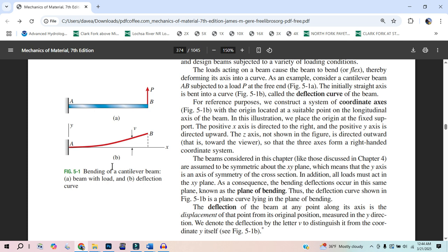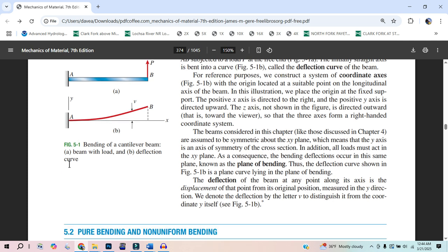But the hardest thing actually is to see that the shear is a negative quantity and the moment starts at a positive quantity, because when we integrate, we can put that line anywhere. Then we have to go back and find what makes sense for what we are observing. We go positive and then we drop negative because of the area under that shear.